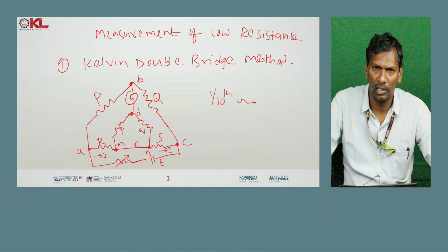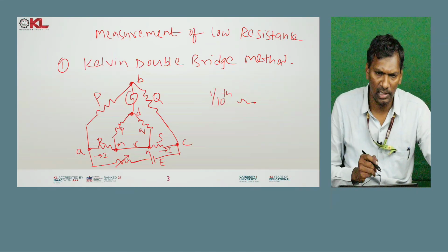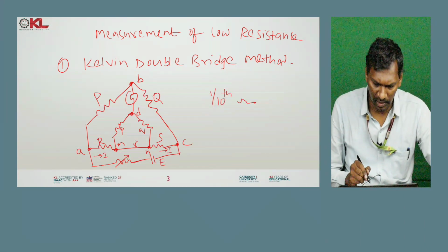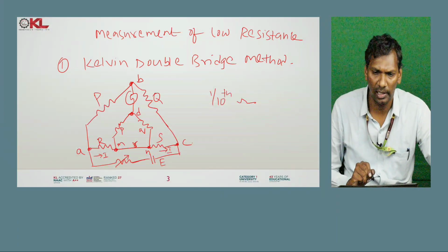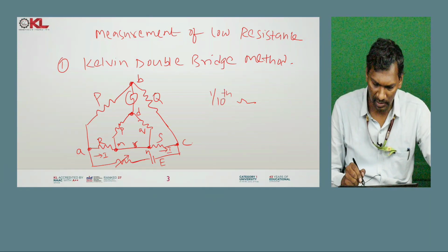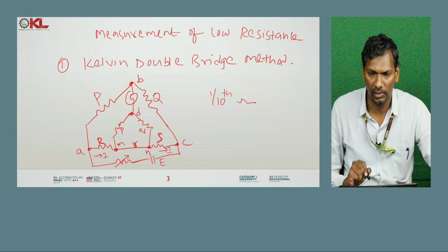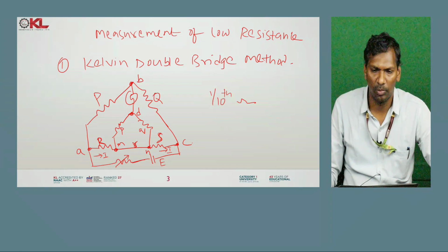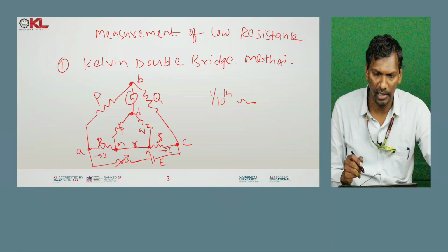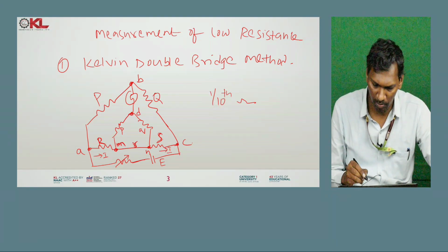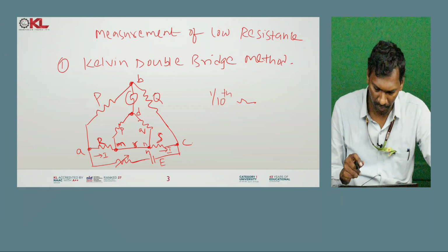Coming to the theory of operation, let's consider the bridge as per this circuit diagram. Here small r represents the resistance of the lead that connects the unknown resistance R to a standard resistance S. So this is the unknown resistance R and this is the standard resistance S. Two galvanometer connections, indicated by the dotted lines, are possible: the connection may be either to point M or to point N.